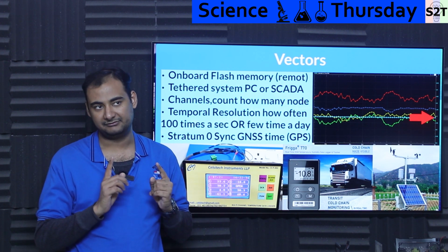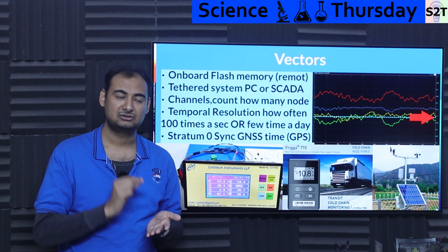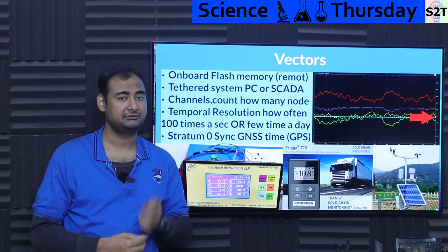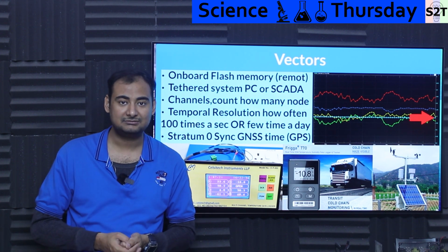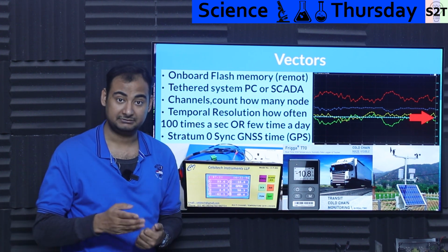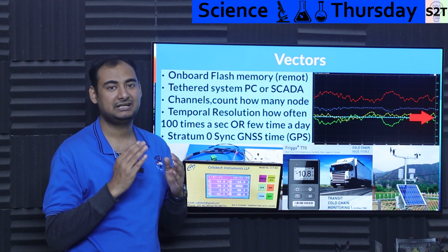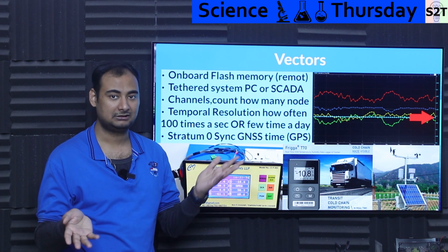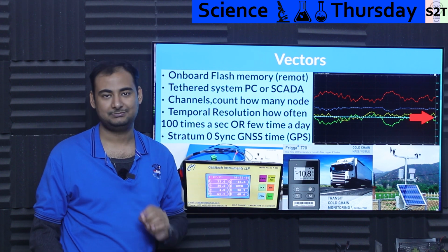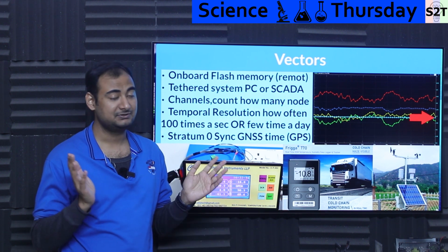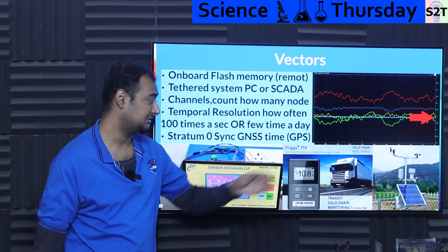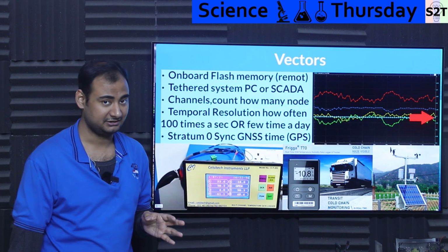But yes, without continuous power on, clocks drift. And you may be like, what if I put in a coin cell? Again, you can do that, but that's an extra hassle. And again, it drifts like crazy. Without an anchoring of that data, you are just lost. Or you can just, hey, put a small GPS unit there and forget about it. And GPS units nowadays are very energy efficient, especially if they are outdoors. Don't even count their energy use.